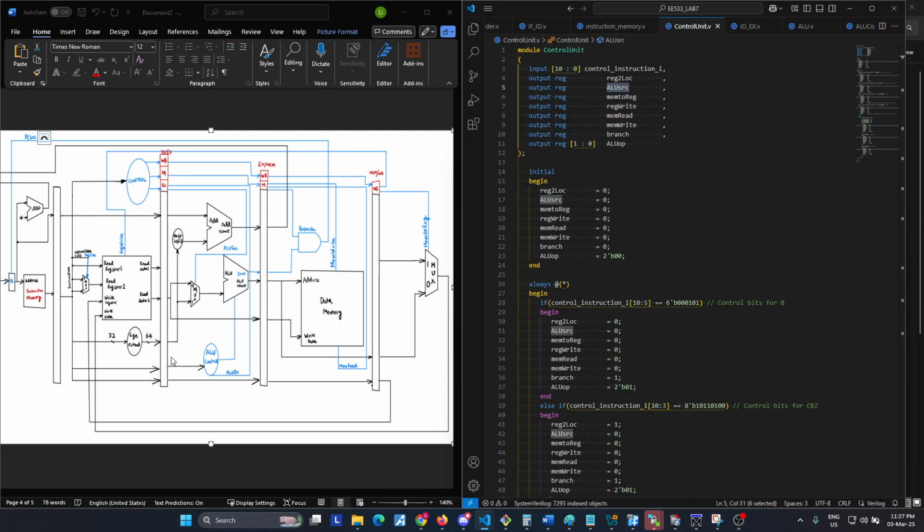If it's an immediate instruction, we'll need the direct number immediately. So for example, add +8. The 8 number will be selected for this mux. Otherwise, if we need 2 operands, the next second source operand will be selected. Mem2reg selects whether this is a memory operation or a register operation, and based on that, we'd select whether to write into the reg file or not.